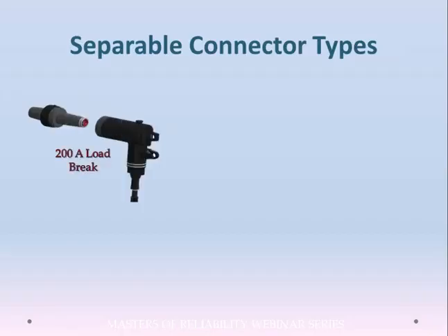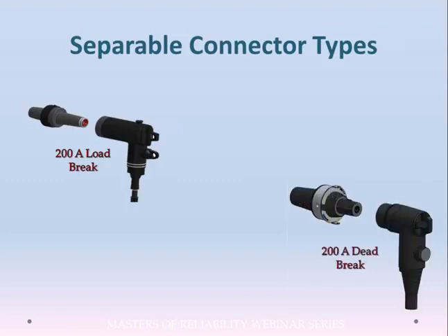So the separable connector types, the first type that I'm mentioning here is the 200 amp load break, because most people are most familiar with this. But the reality is the 200 amp dead break system was really the first, the forerunner of all separable connectors.